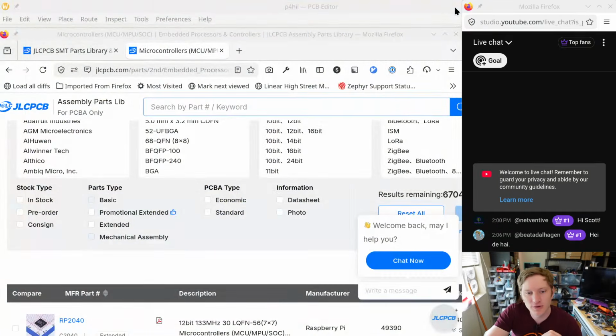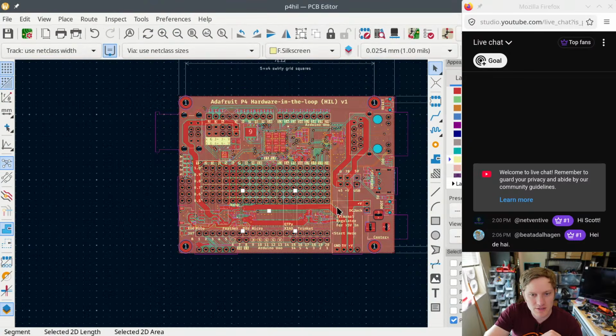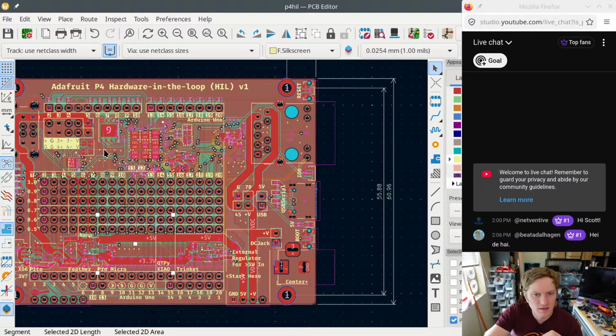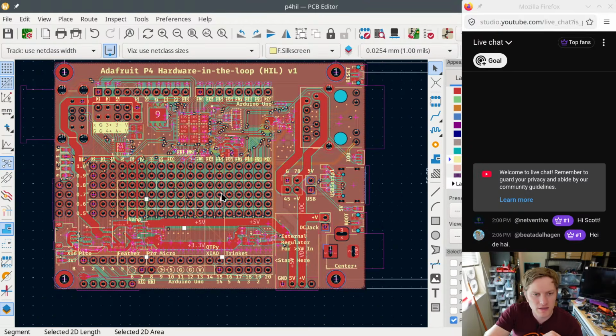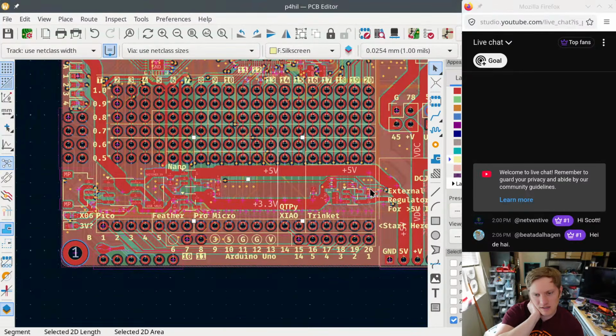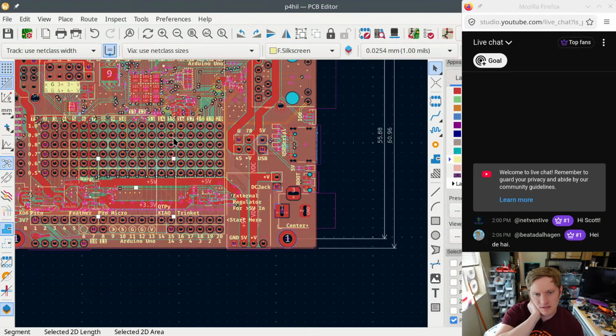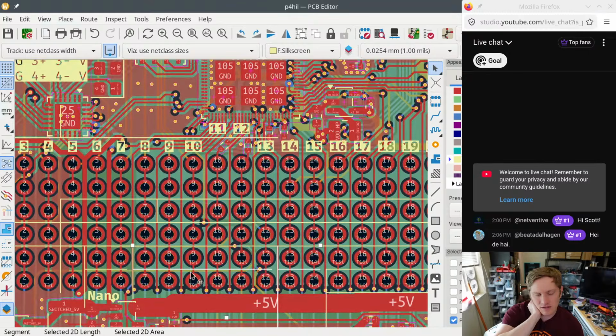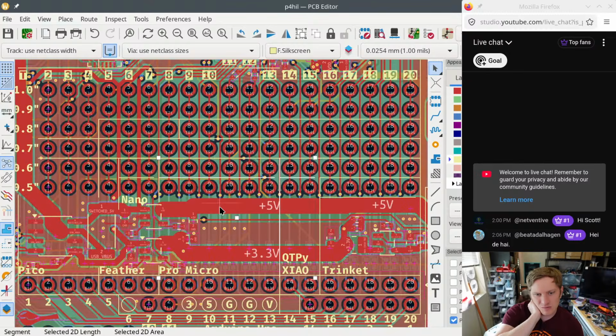If we look at it, it's a 4-layer board. And actually, we can fix the thing. I tried to do power on the outside, and then we also have a ground plane. So big fat power traces, because I'm thinking we're a root hub, so we've got to get as much power as we can to our USB devices. Our switched 5 volts goes out this way, past the resistor for the INA219, and then there are 2 power switches here, and then 5 volt power goes into 3 volts, and all of these boards are connected, plus you also are running lines down to the bottom row.